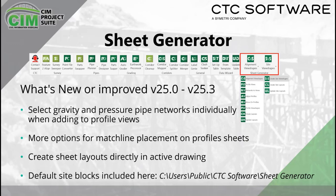And with our sheet or our site tool, the newest tool there, we do include default blocks. They're located at the location you see there, C users, public, CTC software, sheet generator. And if you're going to use a default as it is, you will need to leave it there. You can edit it all you want, but it will need to be edited there. Once you edit it, you can put it in your drawing, and then you can grab it that way.